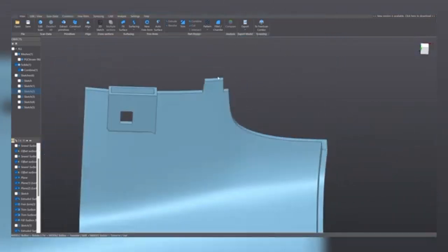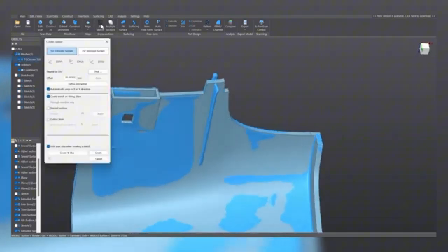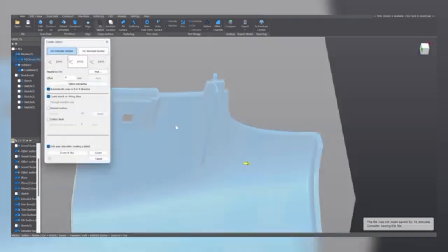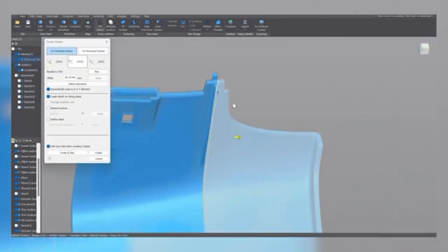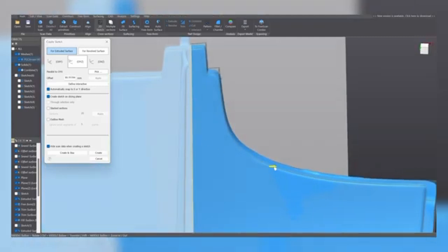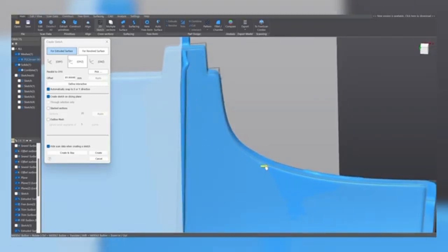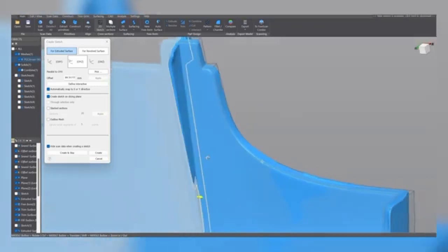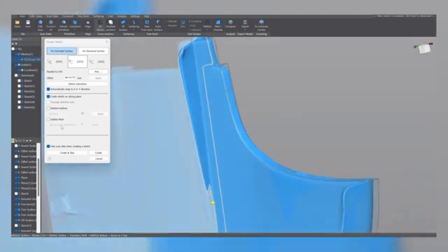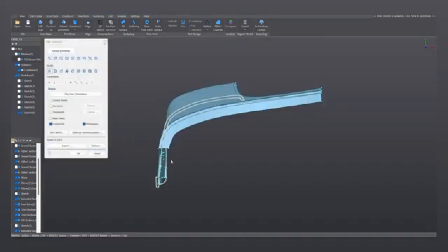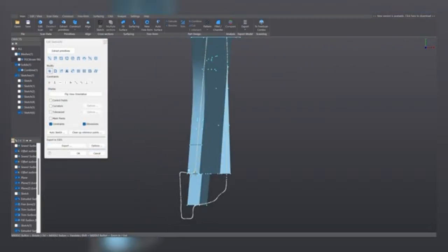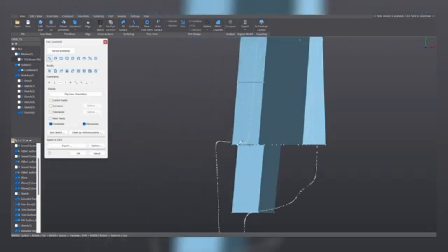And now let's focus on this other shape here. The process, as you might expect, is the same. Just create the 2D plane and place this slicing plane on a suitable position. Create sketch on slicing plane is selected. Click on create. And now we draw a sketch trying to reproduce the shape of our original body.